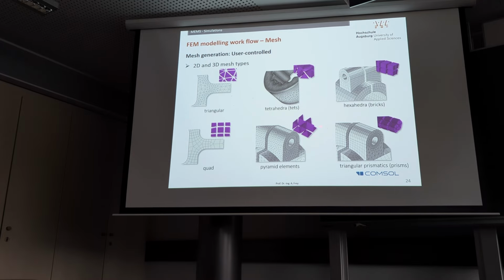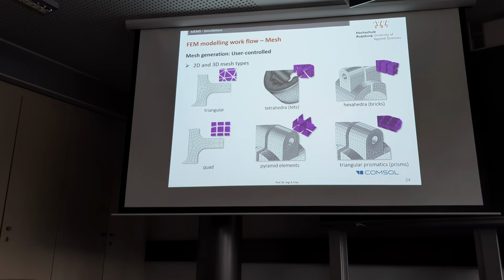But you have to keep in mind, if you try to do it with these elements, it may happen that you start the meshing process and then it stops and says it's not possible, or gives some ugly message, which you could always resolve by going back to the tets or triangular elements.